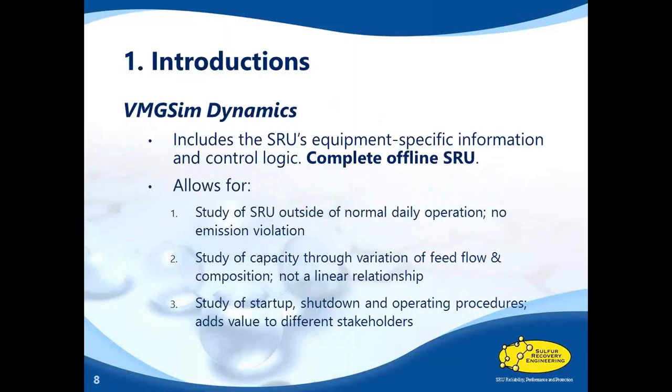We can study the effects of operating the SRU outside of normal daily operation, completely without the worry of emission violations. You don't have to worry about getting that slap on the wrist because, oh, well, I wanted to operate my SRU at maximum capacity just to see what would happen. Next thing you know, I realized something was undersized, my SO2 emissions went out of whack, and now I have to pay a fine. No, all of that can be done with this complete offline SRU tool, the tuned dynamic simulation.